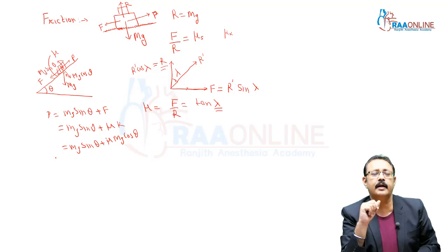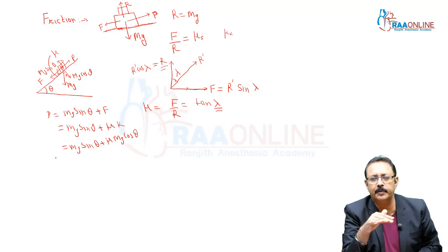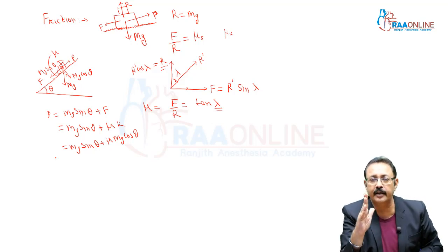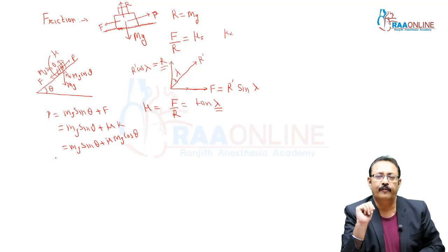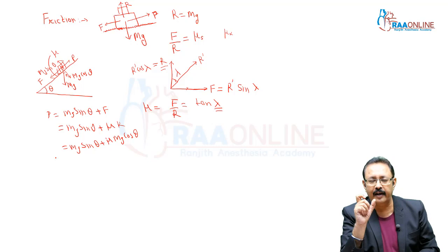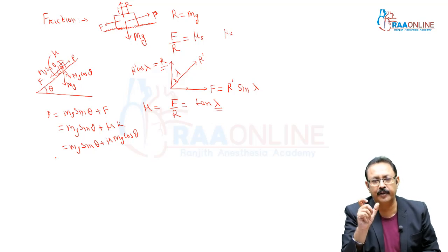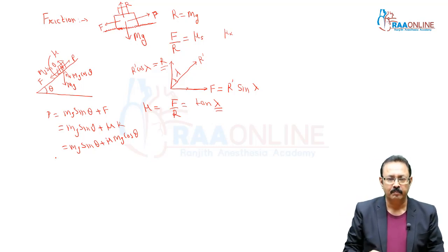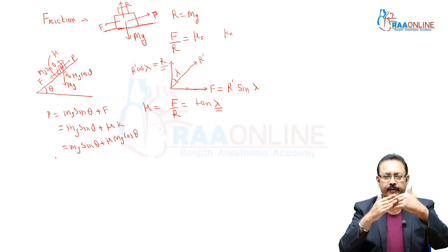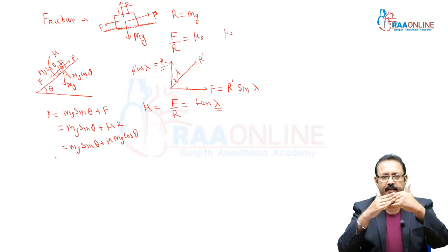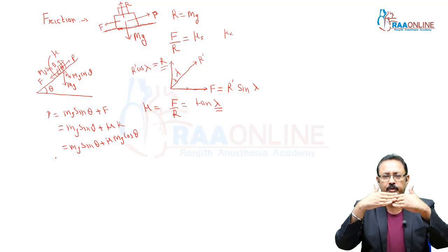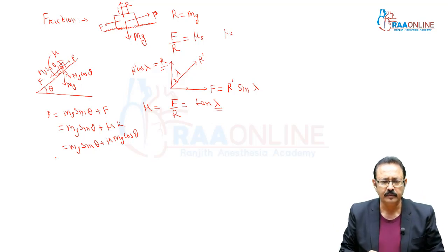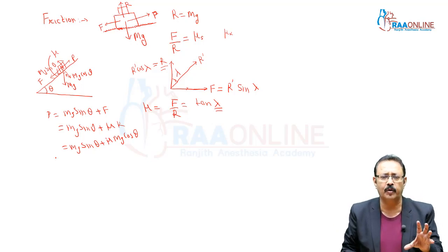You can decrease the friction by polishing the surface. But if you polish beyond a limit, it will increase the friction. Why? Due to strong adhesive forces, it will increase. Because molecules of the two surfaces will attract each other and they will now oppose your motion. So this was all about friction.